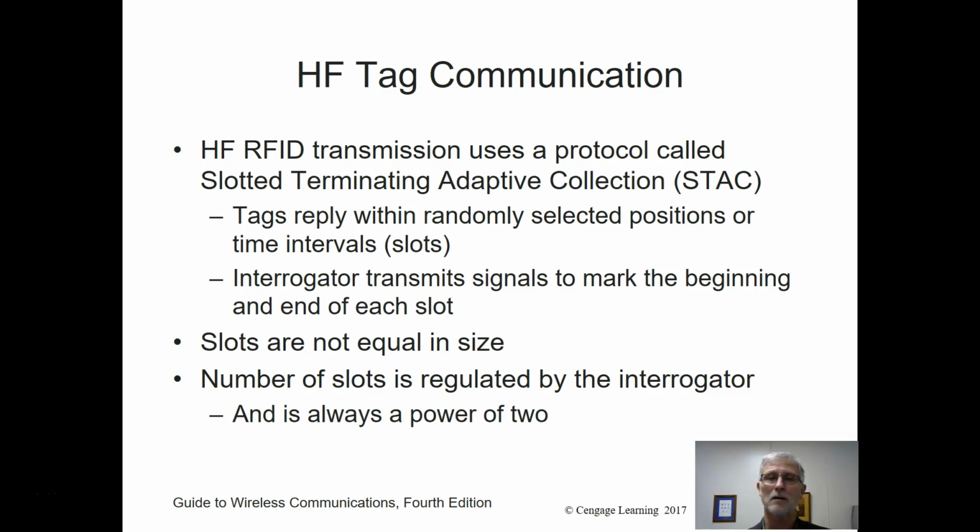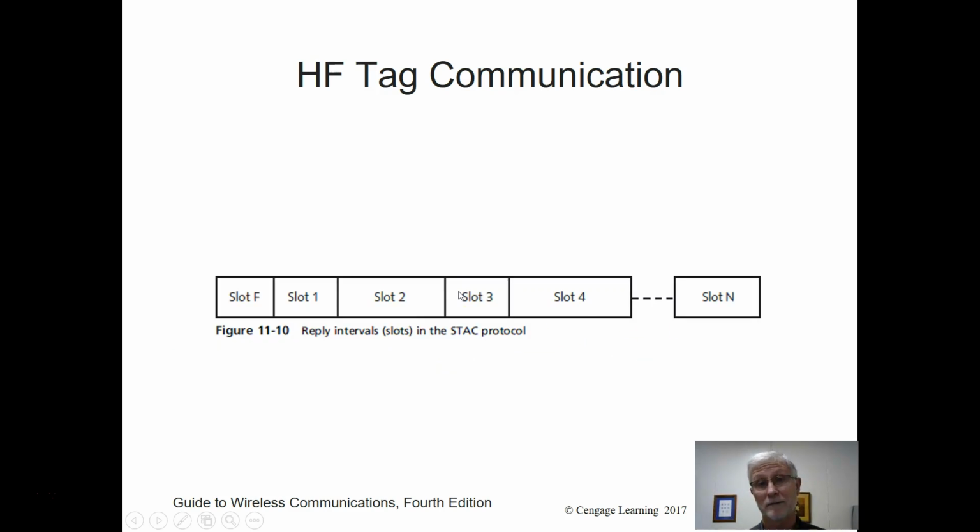It uses what they call slotted communication. Basically, it's a tag where you're assigning time intervals or slots to know when you're going to be broadcasting. So the interrogator or the reader transmits signals to mark the beginning and the end of each slot. Slots don't have to be equal size, and the number of slots can be regulated by the reader.